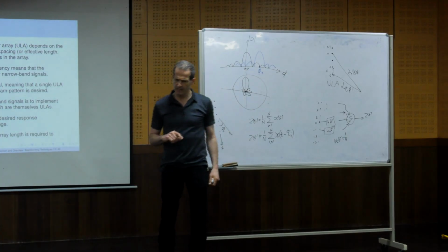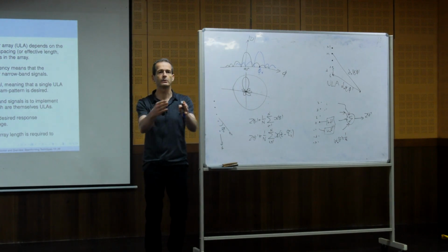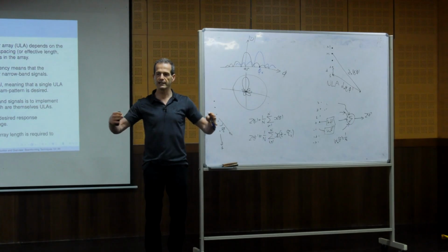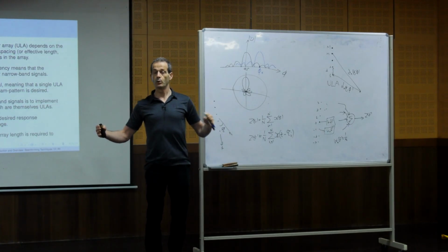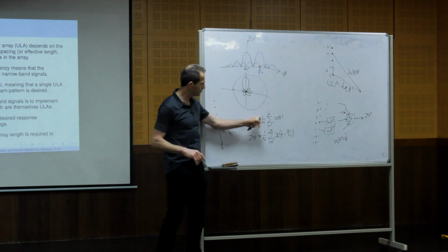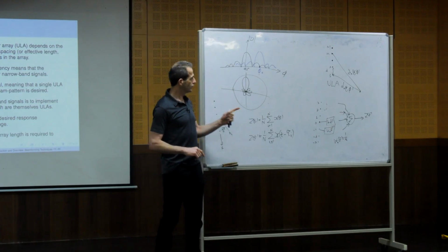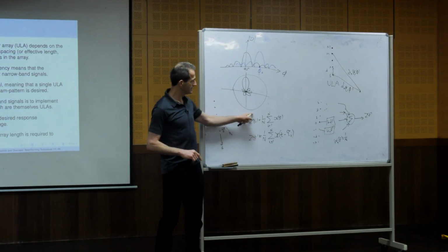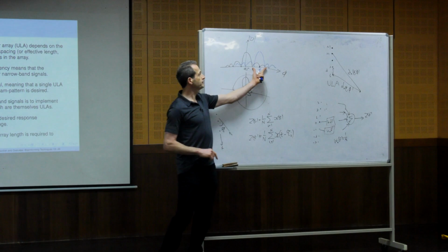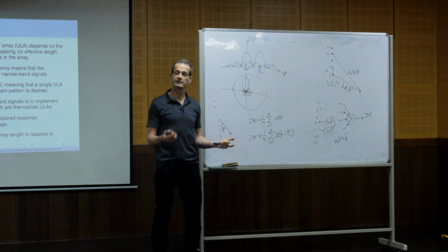Now suppose that when you go to high frequency, it's more narrow. For low frequency, it's wide. Which means that when I get the output signal at the output of the beamformer, for low frequencies the main beam is wide, so I will get the desired signal.